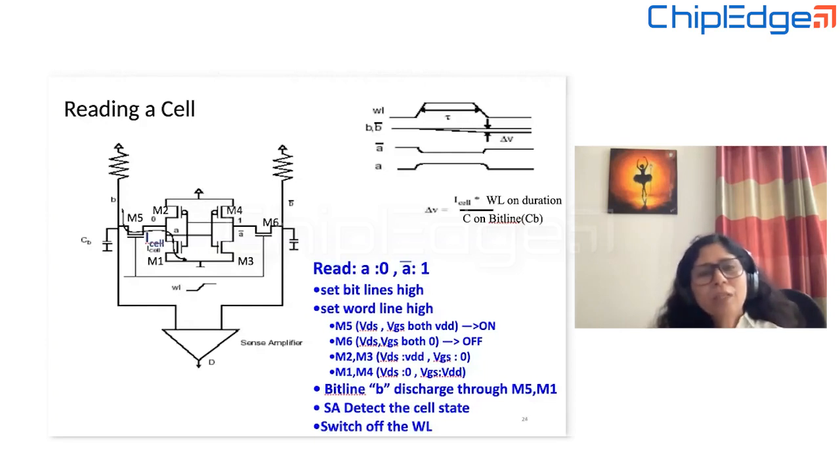And when we say high speed, it means how much frequency the user can get. As I told you, nowadays in the lowest nodes, people are achieving up to 4 gigahertz, 4.5 gigahertz speed from the memory. So after one cycle, at the next cycle, what is the minimum gap you can keep? Let's say you can keep 250 picoseconds, it means you can operate at 4 gigahertz. So this is what we mean by high speed.